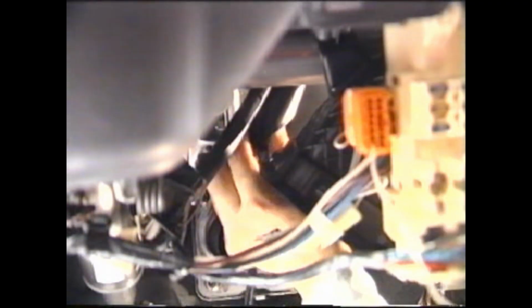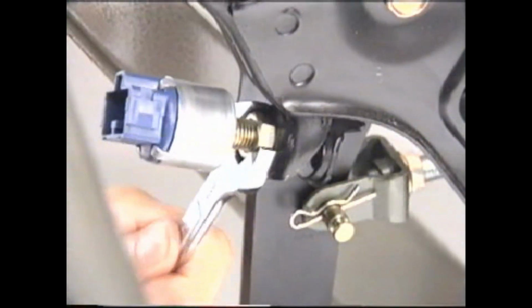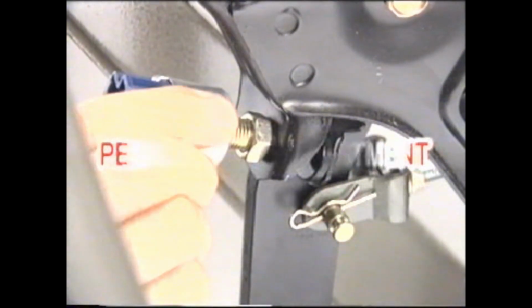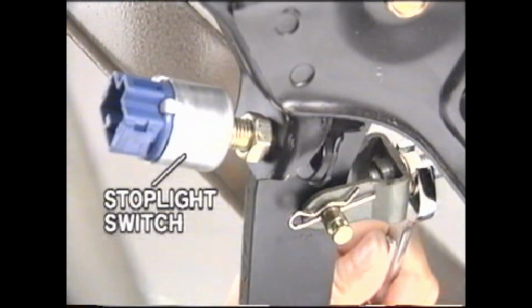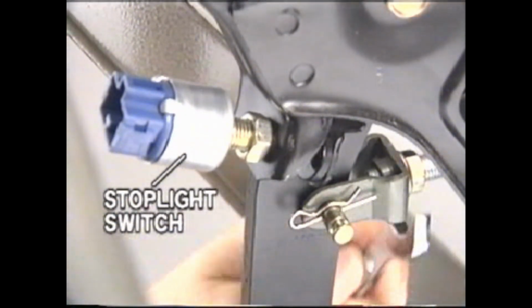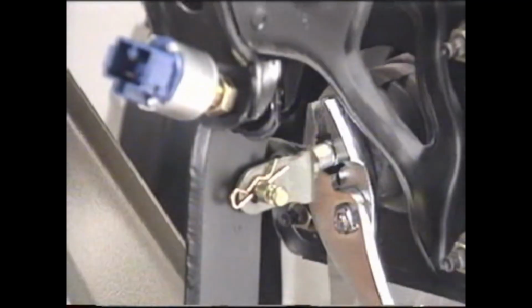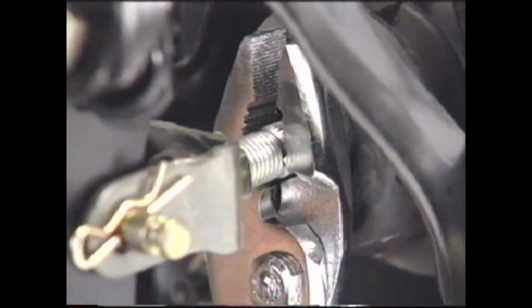Remove the wire connector from the stoplight switch. Loosen the lock nut of the stoplight switch and turn the switch itself 2 or 3 times to loosen it. Loosen the push rod nut and adjust the pedal height by turning the push rod.